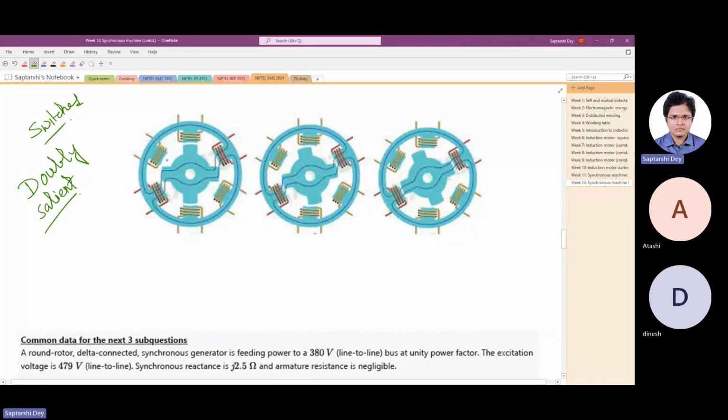Suppose this rotor is rotating in this direction. When this winding is excited, it will pull the rotor towards itself, so that the reluctance is minimized. And as long as you see it reaches here, say in the third diagram, if you see here, now if you turn on this phase, it will keep rotating in this direction. So this is the philosophy of switched reluctance machine.